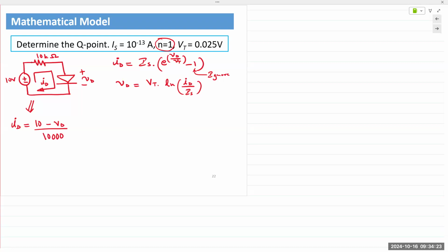Remember, same with the graphical analysis, right? We had a device characteristic curve, but 2 unknown variables. So we drew a secondary line in there, and we call it the load line. The intersection point of the 2 gives us the solution to the diode values. We're doing kind of the same thing here, but just mathematical calculations. We have the device equations, and then we are writing a secondary equation from our circuit.